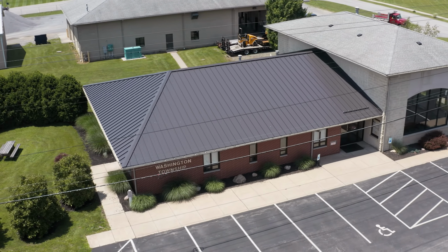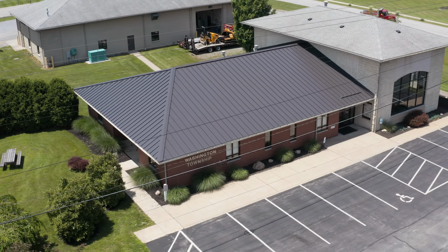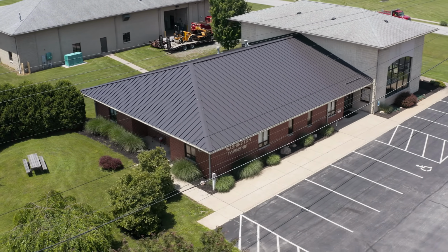They matter because, as we talked about in an earlier series, winds affect different parts of your roof at higher speeds, right? Your corners are going to take basically a double whammy from both sides when it comes to wind, so they're going to take the most force that the roof is going to see. Your perimeters are going to be the next highest area that is going to see the most wind, and then the field is going to see the least amount of pressure. ASCE 7 is going to give you design calculations for different areas of your roof, based on the different loads that it's going to receive. Zone 1 is going to be the lowest pressures that you're going to need, and zone 3 is going to be the highest pressures that you're going to need.